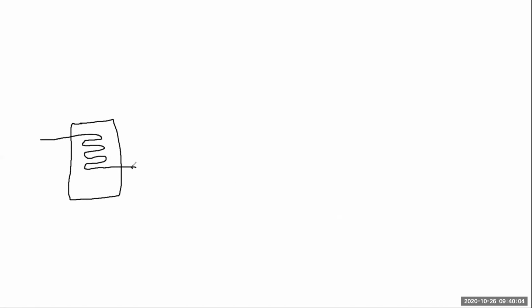This vapor leaves here as saturated vapor, and this is returned back again to the power plant as saturated liquid. So this is from power plant, and this is to power plant. So that the mass flow rate in the power plant is not affected, but we are receiving saturated vapor, we take the latent heat of condensation and we send it back as saturated liquid.